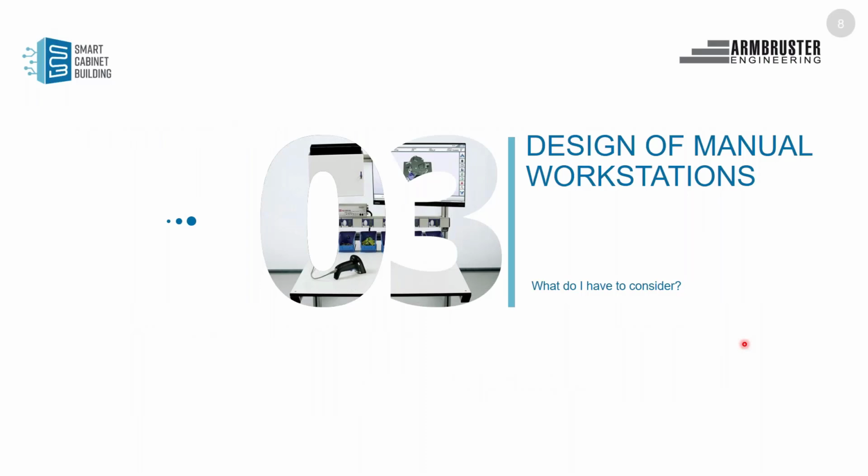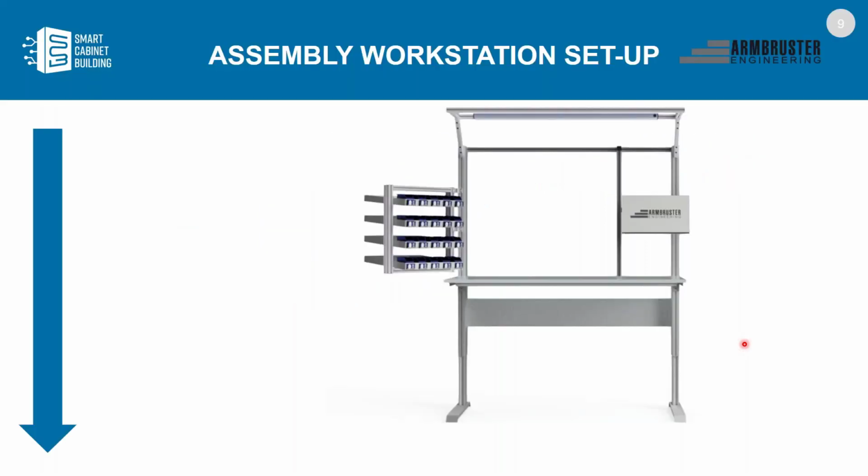All right, let's now take a closer look at the actual topic of designing manual workstations. First of all, we need to know which products I want to produce at the workstation. Why is it important? I need to know in advance which parts I want to keep on hand at the workplace. Have I planned enough space for the boxes with all the parts? Depending on the application, it is advisable to use a swing frame, as you can see here on the picture, to have everything in the best ergonomic reach of the operator.